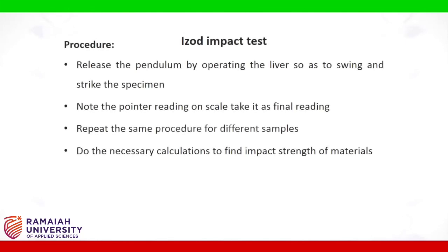Release the pendulum by operating the lever so as to swing and strike the specimen. Note the pointer reading on scale, take it as final reading. Repeat the same procedure for different samples. Do the necessary calculations to find impact strength of materials.